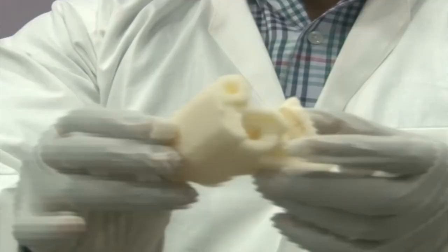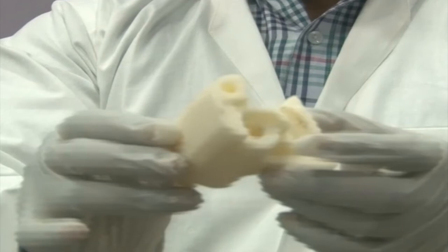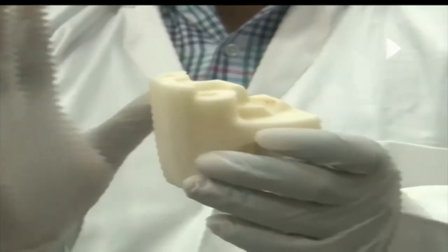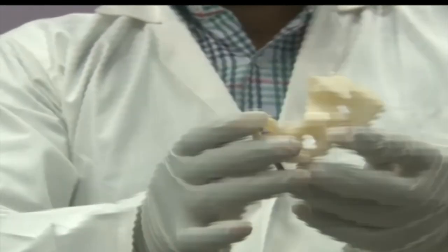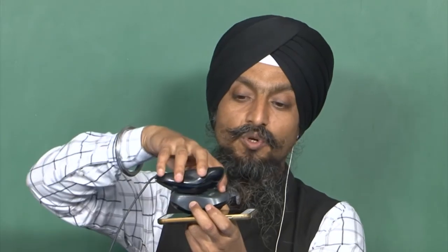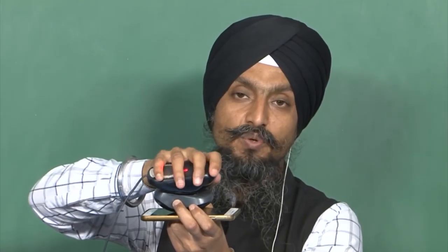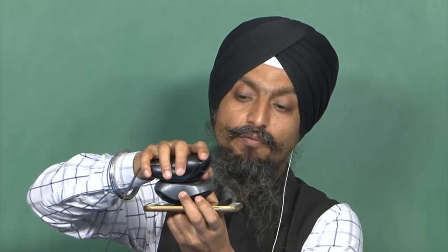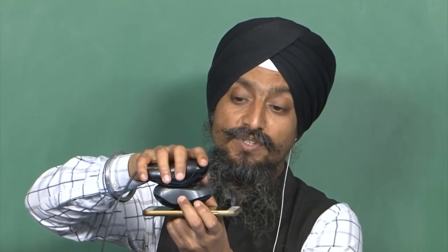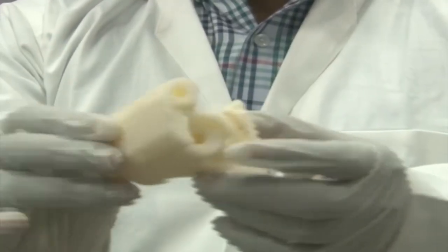In this CAD model, if you see, we use the everywhere command, okay, because it is profiled everywhere, not just touching the bed. For instance, this is the model, like I just said, it is touching the bed. If there is another model, for instance, another thing is manufactured here, this portion in between here is not touching the bed, but it would provide support here as well, because it has to produce this as well. So in case of touching bed, it will provide support here only. In case of everywhere, it will provide support here as well. So the feature is complicated, we use the option everywhere.